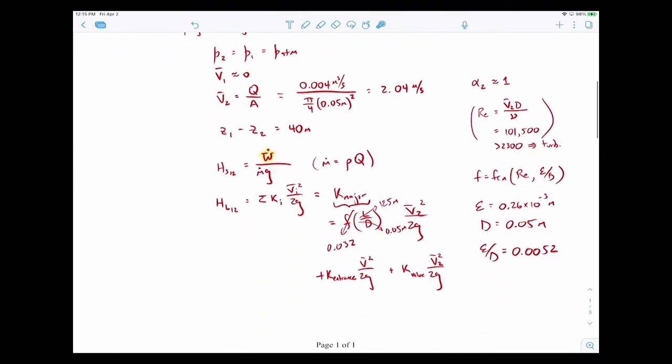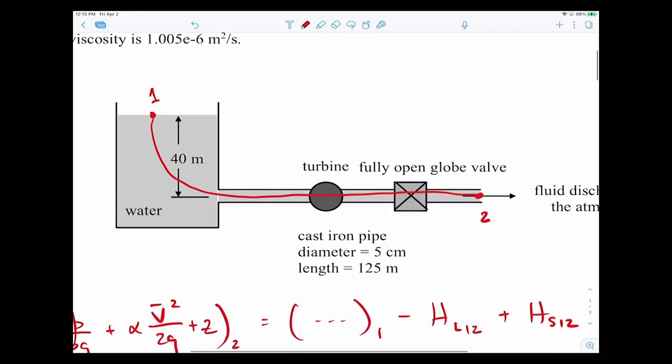Now, let me write that down and then talk about it. So that's still V2. The reason is that's the only well-defined velocity you could possibly use. If you say let's use the velocity upstream, well, what's that going to be? It depends on how far upstream you go. It's not well-defined. The only well-defined velocity is once you've gone downstream of that entrance. When they produce these minor loss coefficients, the tables you use will often tell you what velocity is based on when they created it. If it's not obvious, they'll tell you. So I'll come back to that in just a second.